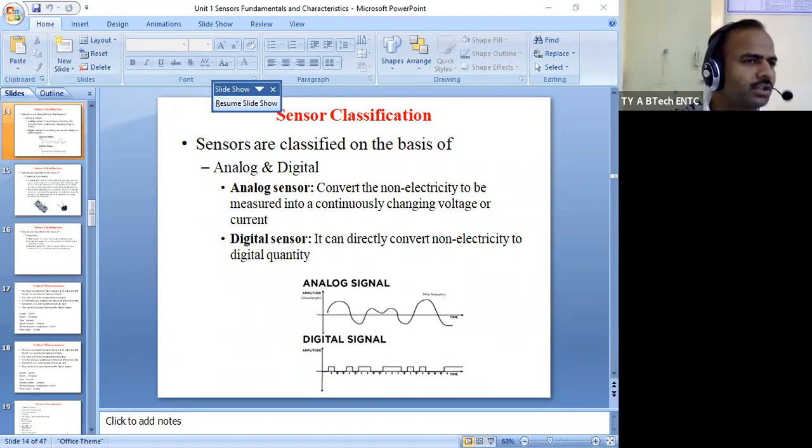In the case of an ultrasonic sensor, when we use it for counting the number of units on a production line or conveyor belt, direct contact is not required. When something cuts the transmission or reception waves between the transmitter and receiver, it automatically disturbs the continuous reception.